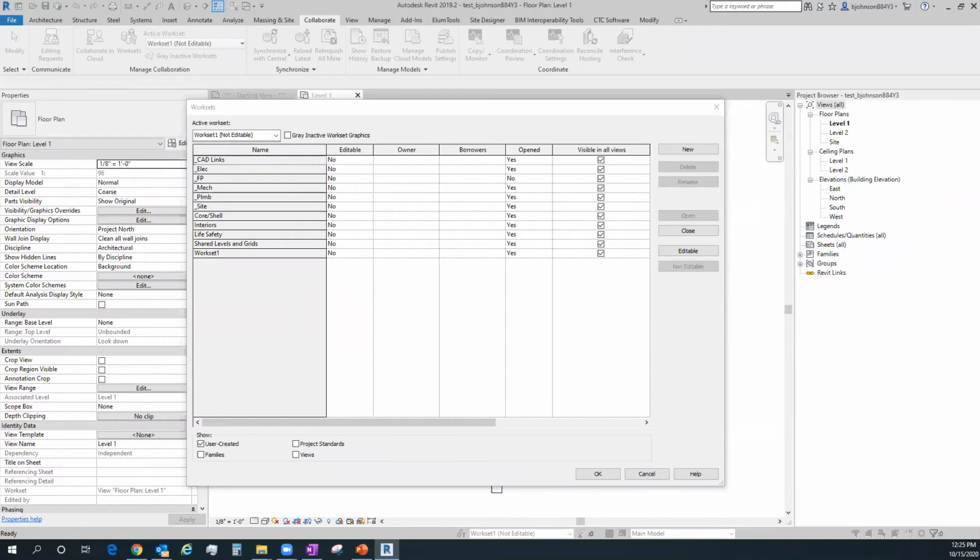So if you have lots of problems with file corruptions, model maintenance is a key thing to prevent file corruptions. Make sure that everybody's working fresh every week to every 2 weeks, depending on file size. It's just a really good idea to maintain your models and make sure that they're working well.